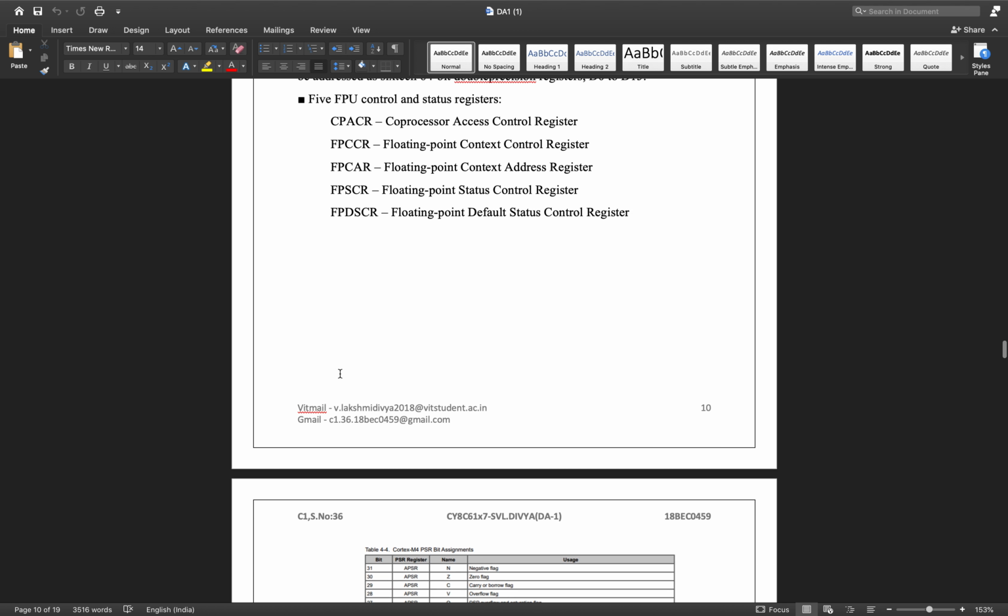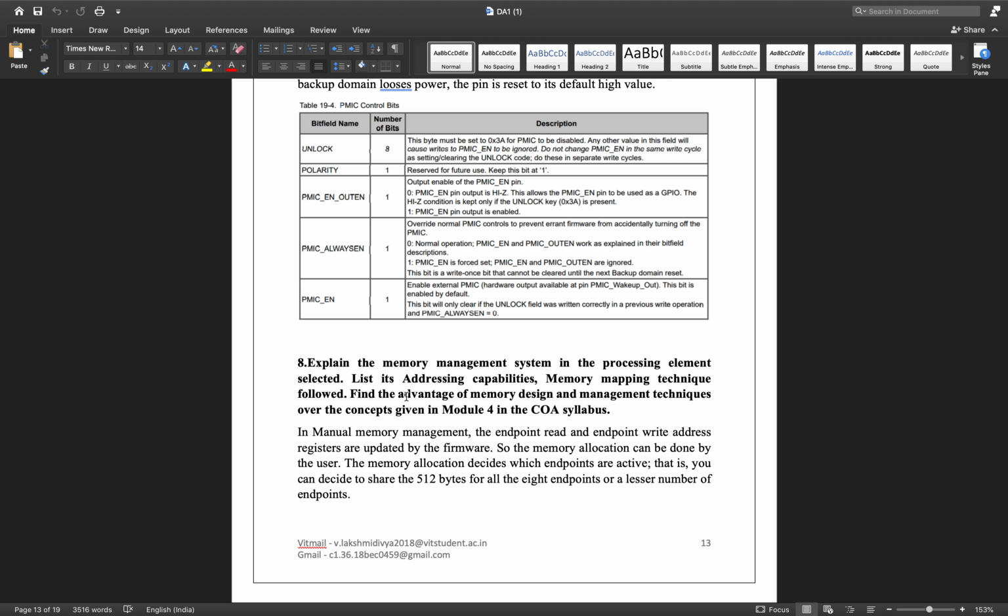Now we are going to talk about the memory management system in the microcontroller. PSoC 6 contains flash, SRAM, ROM and eFuse as its memory blocks. In flash there is 1 MB of application flash and 2 32 KB flash sectors, one of them auxiliary flash and the other supervisory flash, which is S flash, and it also has 2 cache memories. Up to 256 KB of SRAM is provided. The 128 KB ROM, also called supervisory ROM or SROM, provides code for several system functions.